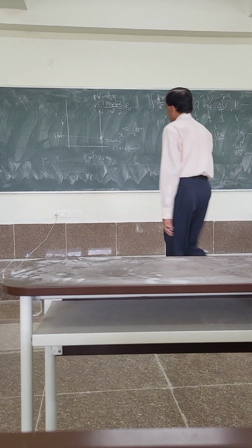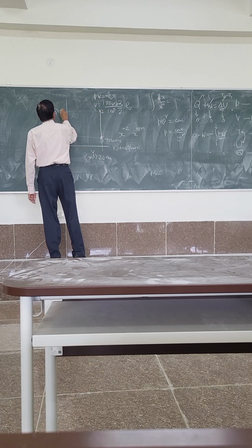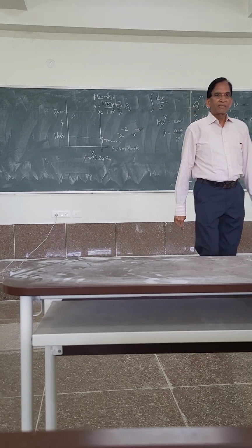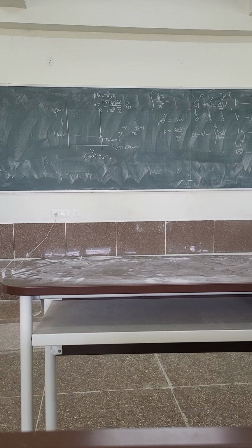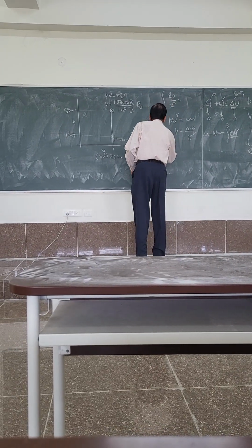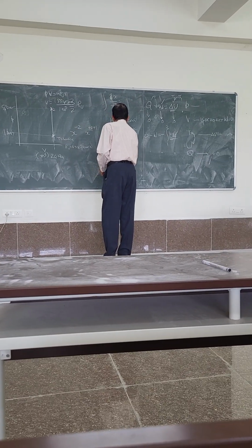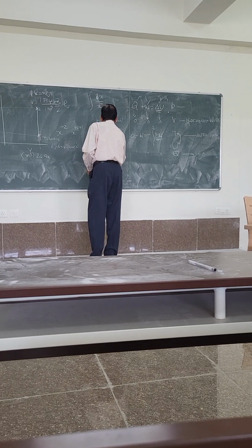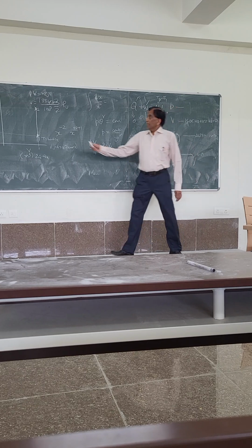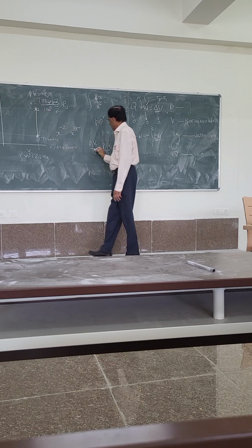Of course, we also said that it is going to be compressed air. How much will be the temperature? So apply the ideal gas equation of state. So we know that P1 by T1 equal to P2 by T2, because the ideal gas equation of state is very important. So that's why I have to use it.